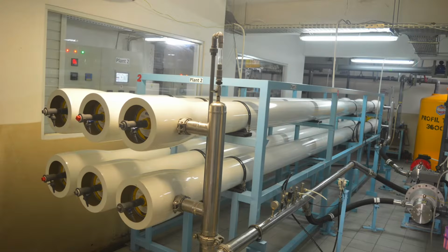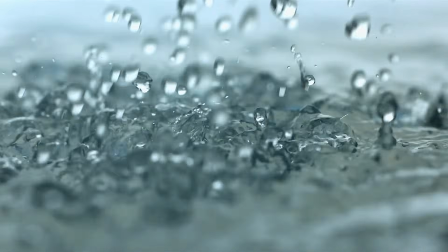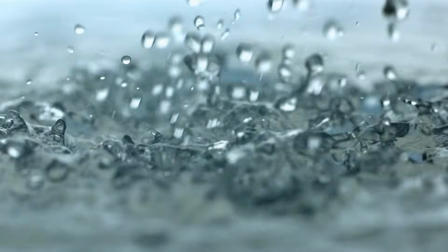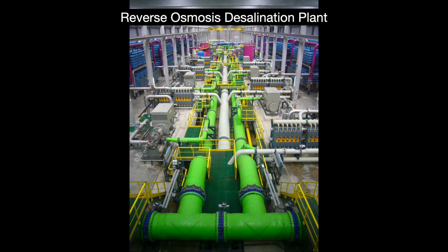Reverse osmosis processes by themselves, so excluding the cost of pre-processing, tend to be more energy efficient. Thermal processes need about 10 to 15 kilowatt-hours per cubic meter of water. RO, by comparison, needs about 5 kilowatt-hours per cubic meter. On the other hand, thermal processes are very scalable, and their operations far more reliable. The water doesn't require pretreatment like with RO. Middle East countries have the energy to burn, literally, and so energy efficiency sadly tends to be a secondary concern.